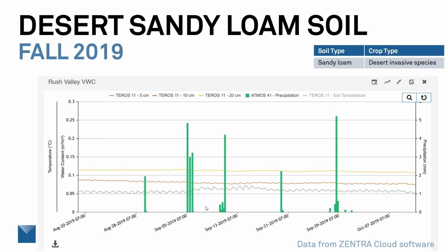Well, I think there are two reasons we're not seeing this. One is that we're just after a very long, hot, and dry summer, where it's very likely that the temperature of the soil, which got up over 40 degrees Celsius pretty much every day, was actually hydrophobic. So the infiltration of water would first require that the surface be wetted by that precipitation event before we get any infiltration.